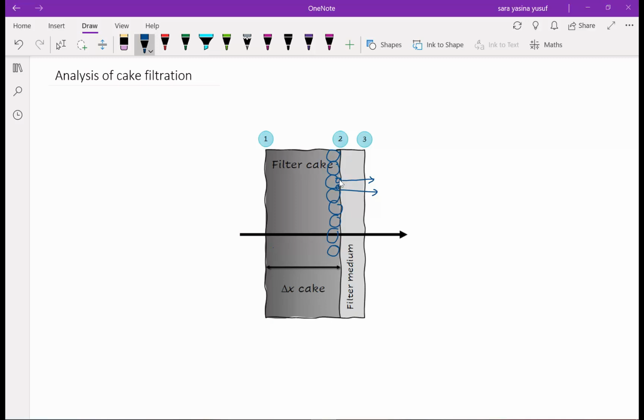The filter cake here will also act as a filtering medium to filter much smaller particles. So when there is a cake, much smaller particles cannot pass through. This means that in the filtration process in a filter baghouse, we depend on two layers of filtration, which are the filter cake and the filtering medium.